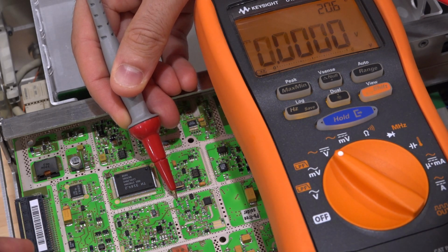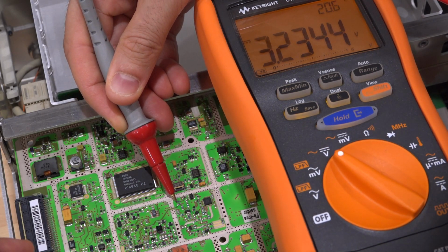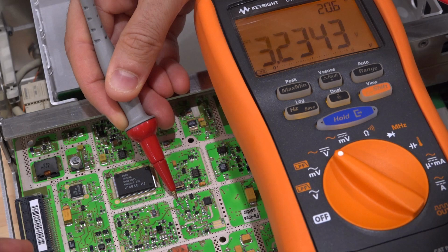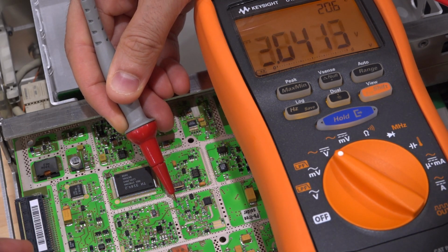But the power supply is coming from this component here. That's just a resistor. You can't see the part on it. It's a 1 ohm resistor. So it's basically a short circuit. If I measure on the other side, look at that. On the other side is 3.3 volts. Now on the other side of the resistor, it's 0.8 volts. That makes no sense at all.